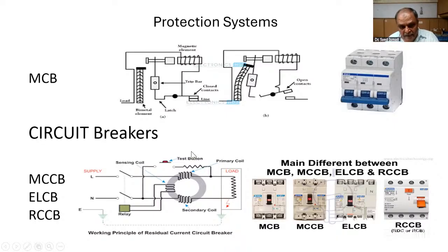Now you have the circuit breakers, MCCB, and protection like ELCB, which is earth leakage current, and RCCB, which is residual current. I will not explain them; these are safety systems. If your wire somewhere touches ground or goes somewhere else, you detect it and it breaks automatically. So remember these words whenever you install. Have you put MCCB? Have you put RCCB? RCCB is better in agriculture than ELCB. ELCB is used mainly in houses, in old items. This is the old technique. RCCB is the latest, from the last, let's say, 15 to 20 years. It's slightly expensive. ELCB is earth leakage, RCCB is residual current.